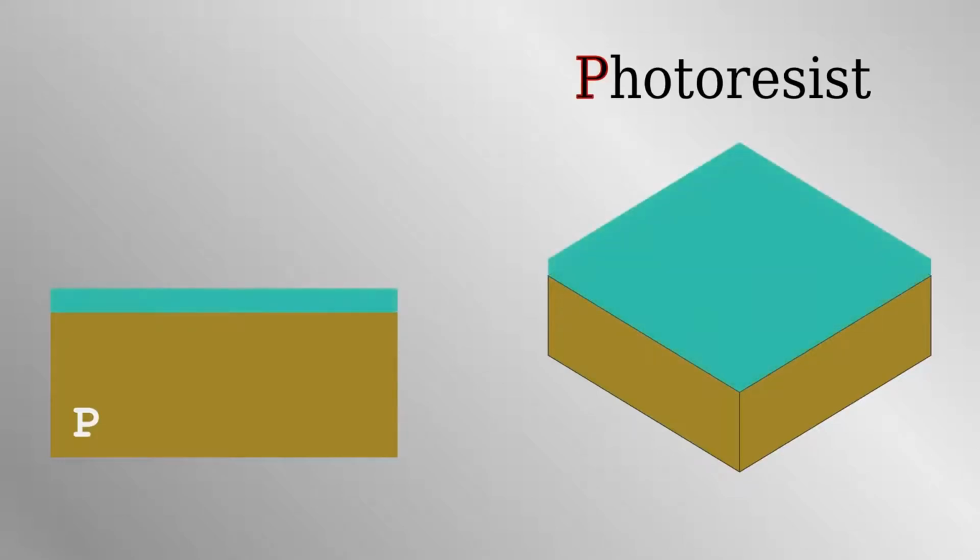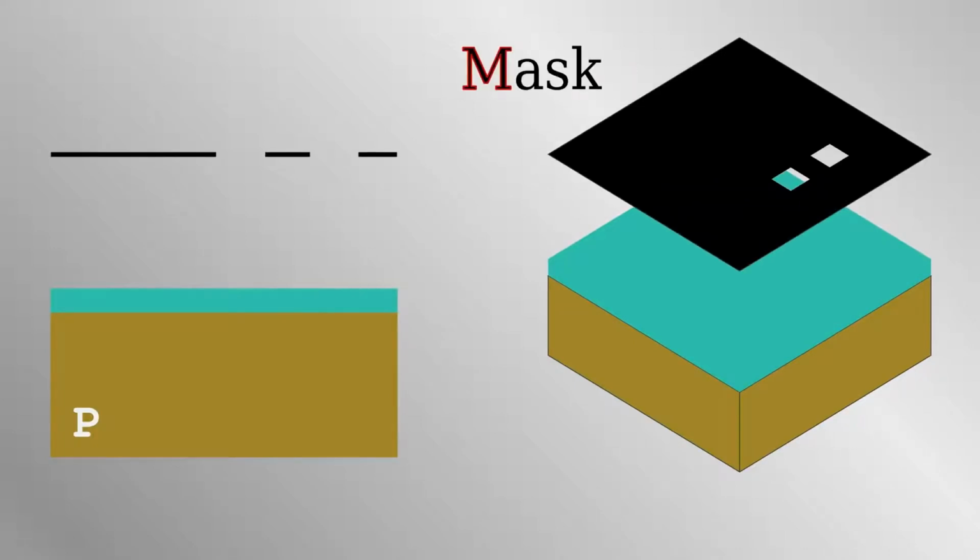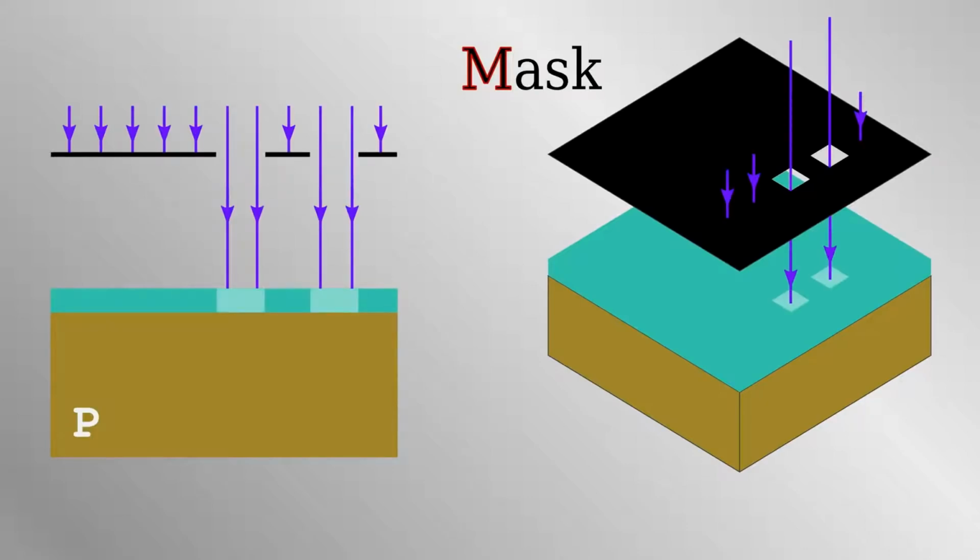A chemical termed a photoresist is deposited onto the die. Light is shined through a mask, exposing predetermined areas of the photoresist. The exposed areas must be the same size or larger than the wavelength of light used. Hence, very short wavelength ultraviolet light is used for lithography.